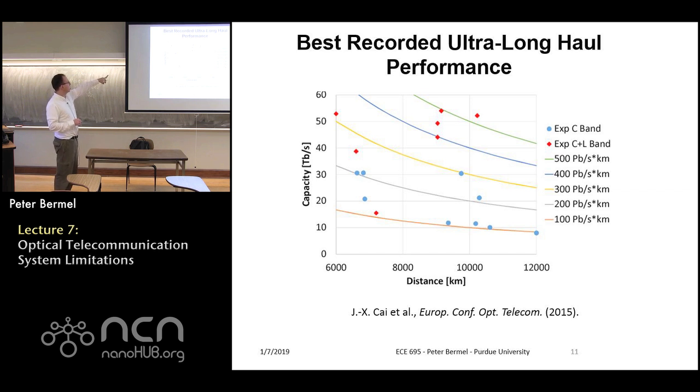And then what they showed basically is that obviously if you have a fair amount of dispersion, then you're going to be somewhat limited in capacity, but you can still overcome a lot of the issues that we were talking about earlier with the combination of fast source, fast detector, obviously the right choice of fiber, and most importantly, good amplification and good limitation of loss, so that the system keeps the signal coming without any substantial distortion or aliasing between different bits in the system.